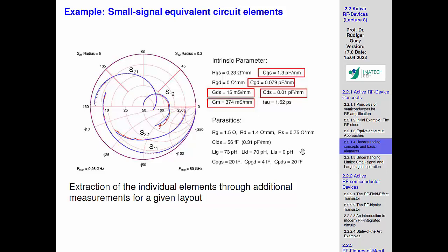And there are some numbers now. So this is something which we would like to look at. So this is now the understanding in very principal terms of the MOSFET. The question is now, what else matters? Yeah, and you see here, for such a device you get numbers, and the point is that these numbers which we just extracted from a DC and maybe a little bit of AC analysis, they work wonderfully also out of these S parameters we talked about.